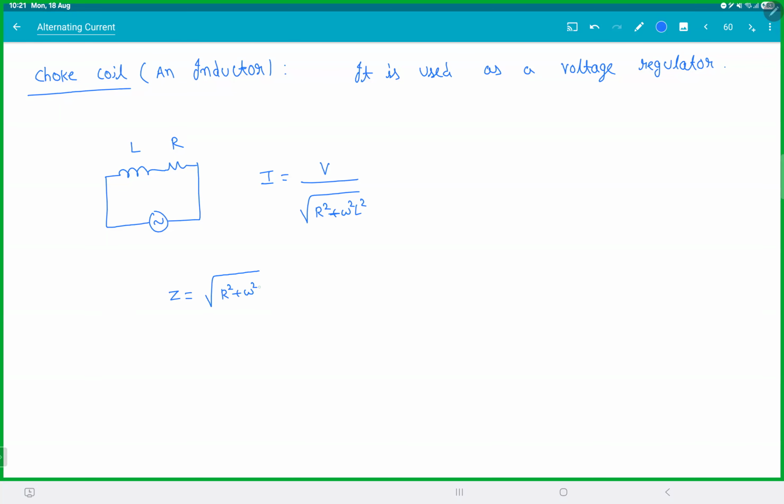So when you're rotating that knob, you're actually changing the inductance. And inductors do not dissipate energy, so you're safe. So by changing L, we can change the current magnitude without additional power dissipation. That's it. So if they say choke coil, that's what they mean.